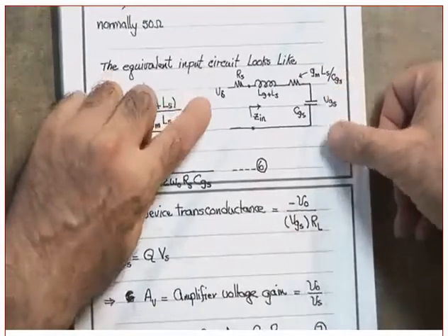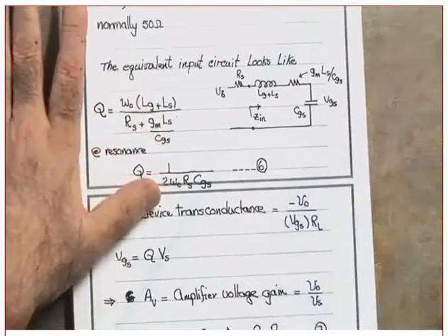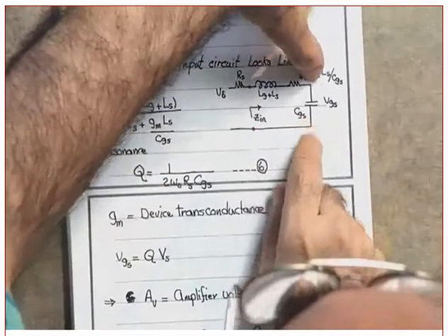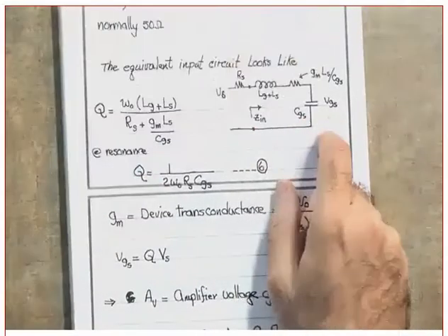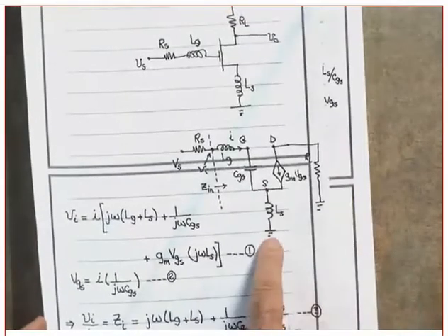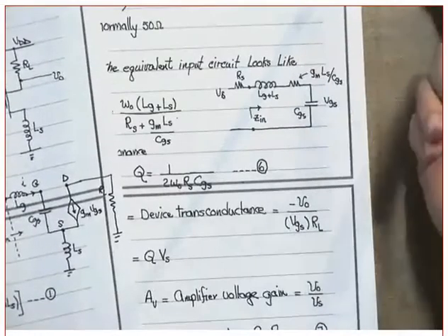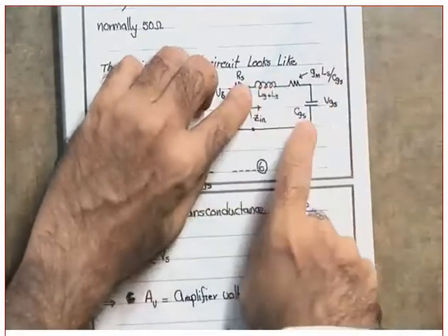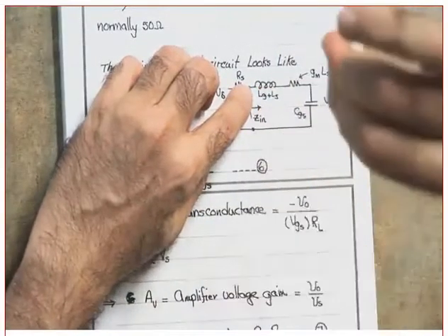Now, let's get back to the circuit so that we can see the gain stuff here. This is the equivalent circuit. Now, remember one thing. Listen to me. Where is the gate? This is now the gate, and this is now the ground. So that's the VGS. You might say, but Professor, the source is not grounded. We already took the effect of this in here. That's why I added this. Okay.